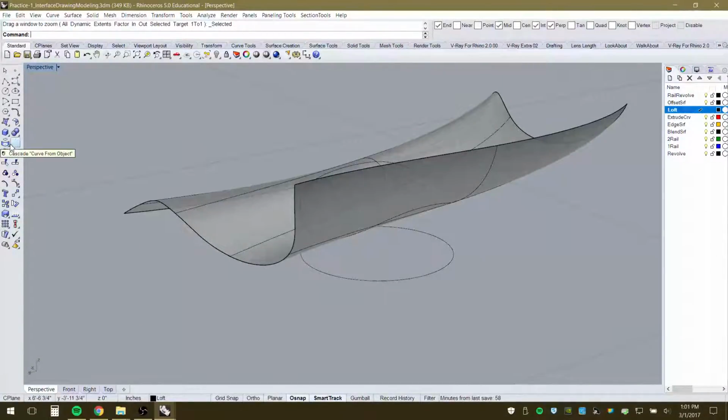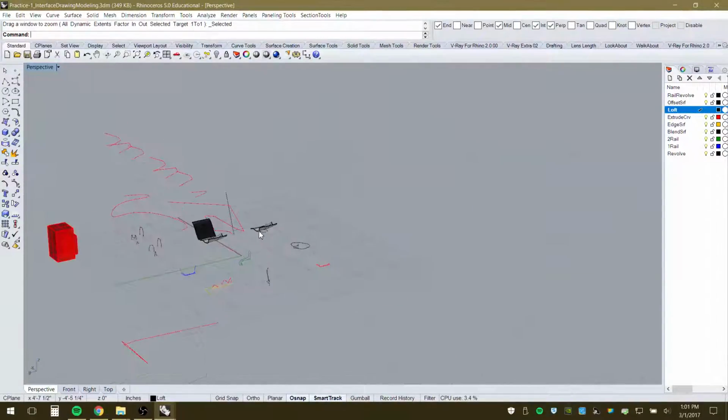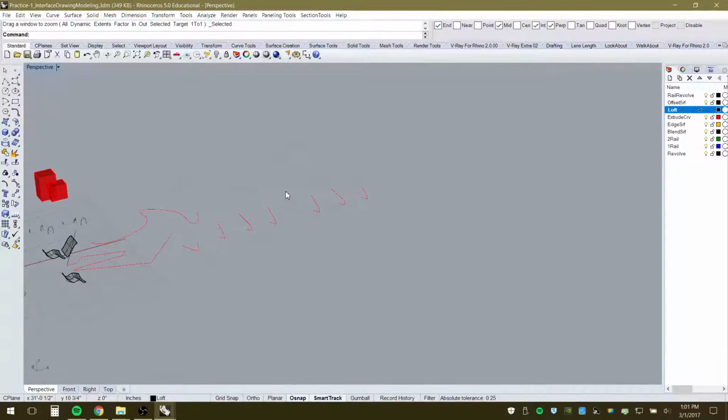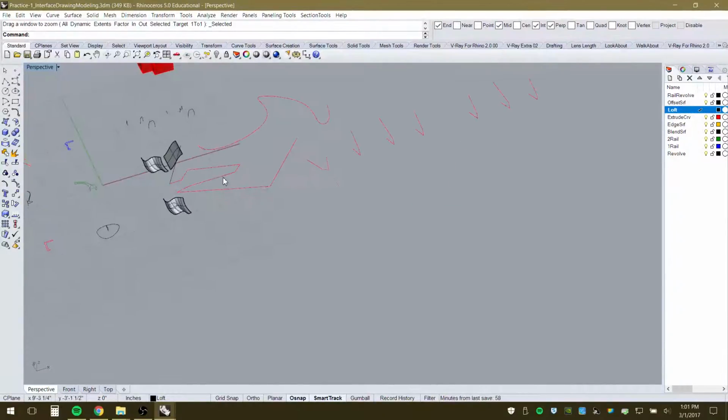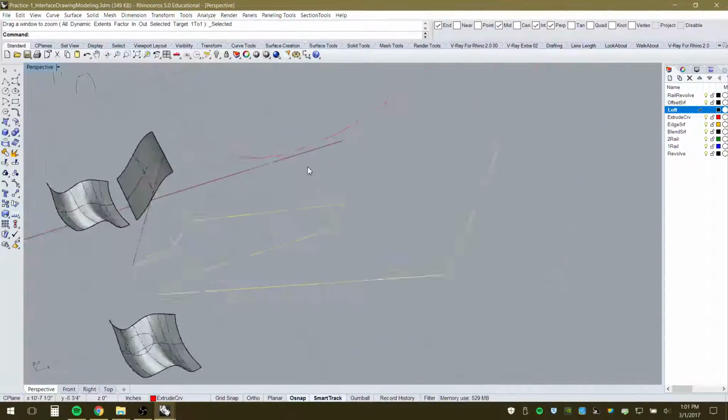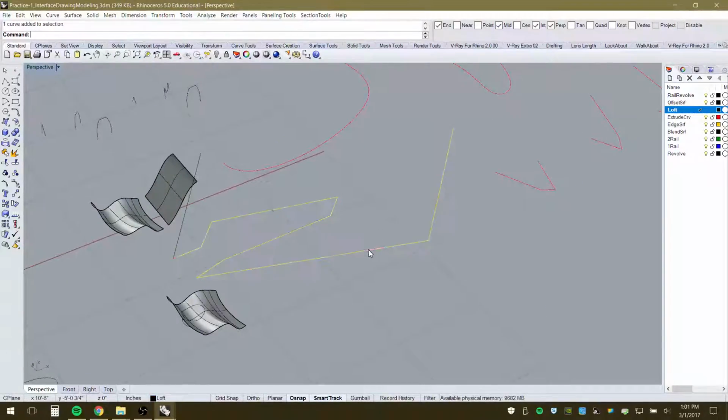Let's see, so that's project. These are mesh tools. I don't really get into using mesh tools, and I don't think we'll cover that really this semester. This is the join tool. You can join lines so that they are together. Let me just zoom in on this. Right now these are already together, and I could explode that. There's the tool right next to join, so the opposite of that. So now I just exploded it, and these are individual lines now.